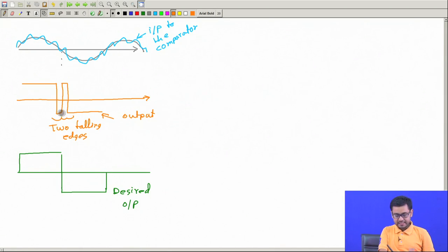So that means when this part of the signal comes, the counter will be incremented by 2 instead of 1. But we want it to get incremented by only 1, because this signifies 1 clock cycle, but here we will get a count of 2, an extra count. Depending on the amount of noise in this transition region, we may have more and more such false edges. So this is not good.